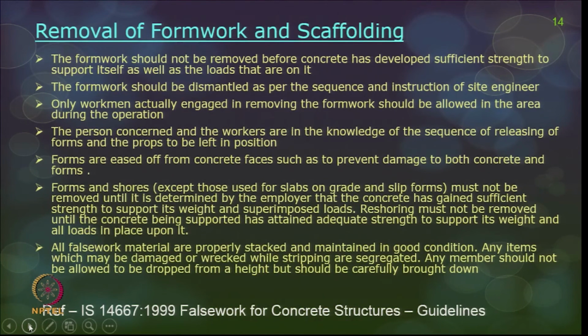The forms are eased off from the concrete faces to prevent damage either to the concrete or to the forms. Accordingly, the forms should be stripped off, and the forms and shores must not be removed until it is determined by the employer that the concrete has gained sufficient strength for the superimposed loads that come onto it.